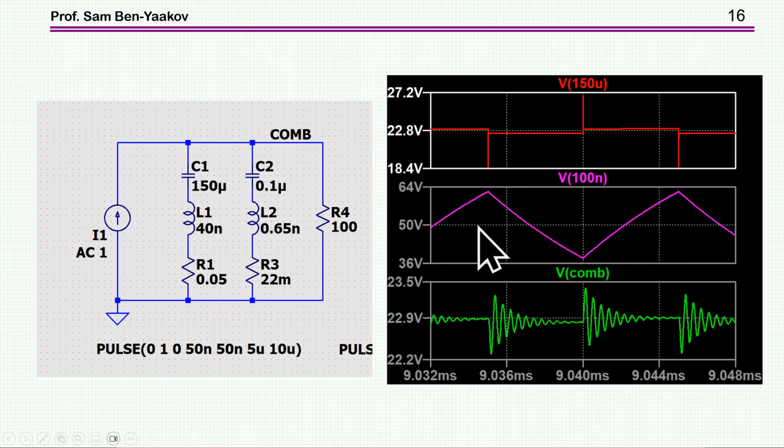And here I'm showing the ripple that you'll get if there is no electrolytic capacitor, just a 0.1. Well, you don't see the spikes, but the ripple is very, very high. Okay, well, it's 15 volts peak. So this is why you need a capacitor for the storage of the low frequency ripple.